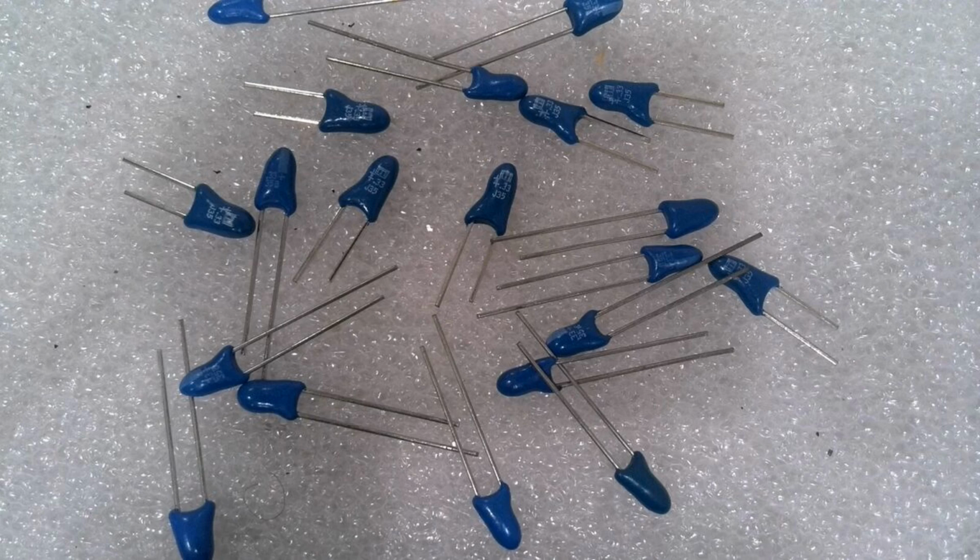1. Energy storage. A tantalum capacitor stores energy in the form of an electric field. When a voltage is applied across its terminals, positive and negative charges accumulate on the anode and cathode, respectively. The thin dielectric layer of tantalum pentoxide between the anode, tantalum, and cathode, manganese dioxide or polymer, prevents direct electrical flow, allowing charge separation and energy storage.